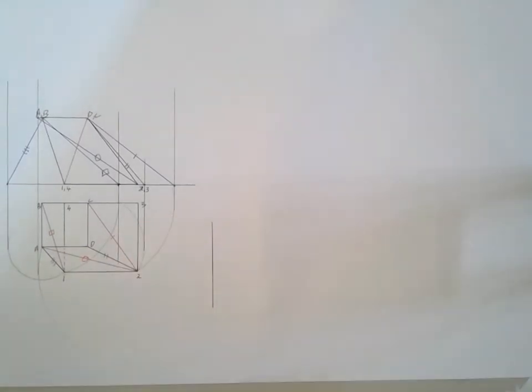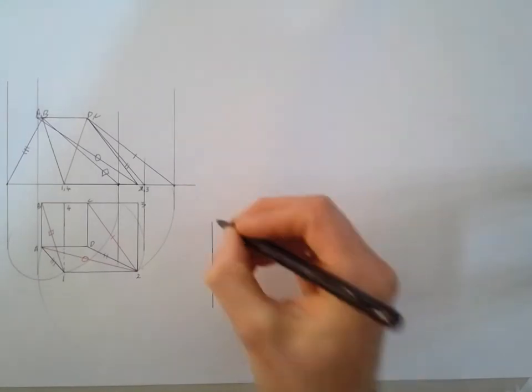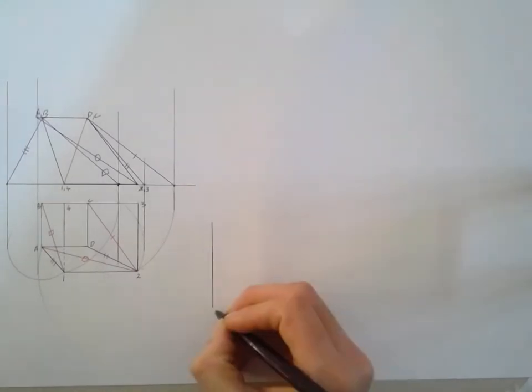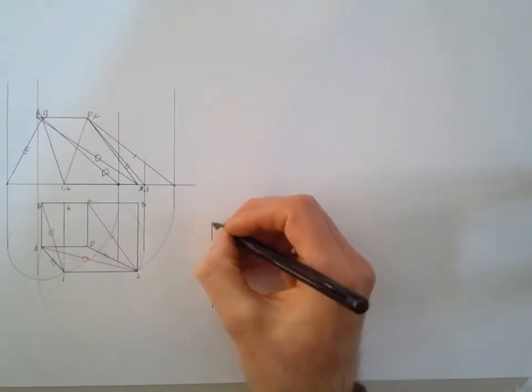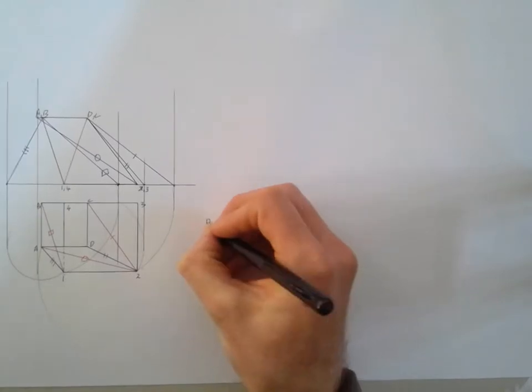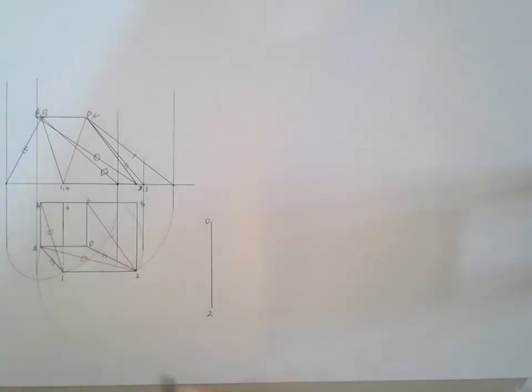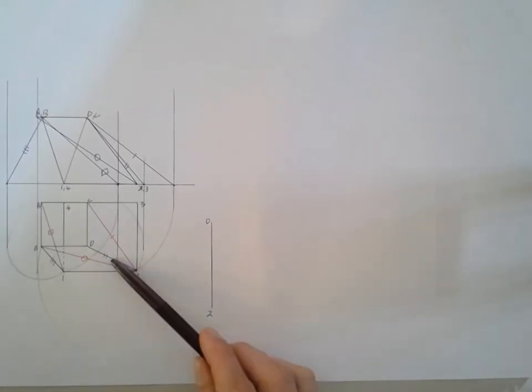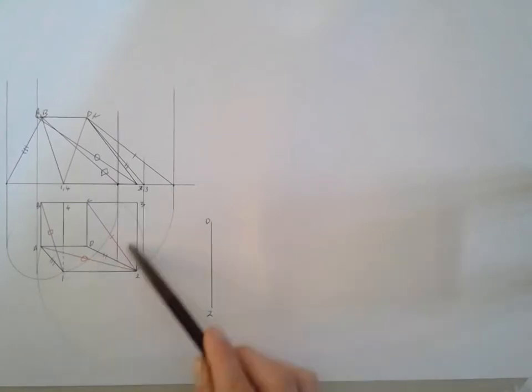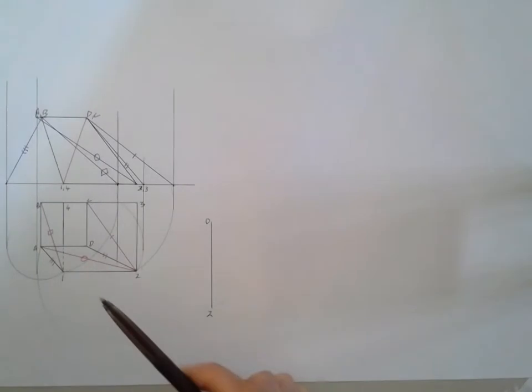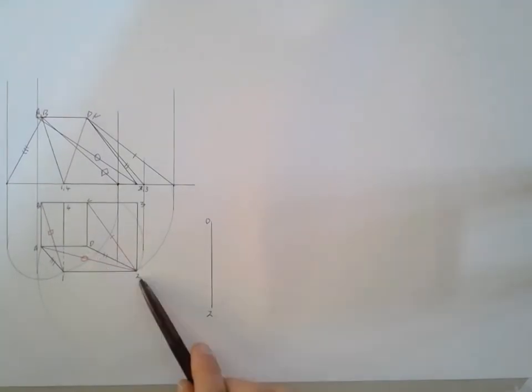And now that line, we want the base points here at the bottom and the top points at the top. So this must be labeled point D, and this must be labeled point 2, so that we've got our line D2, which is this line here. And now generally we work in a clockwise direction unless they tell you otherwise in the question. So I'm going to move from that line in a clockwise direction around and work from triangle to triangle. First triangle that I'm working with is the triangle D2 to A.